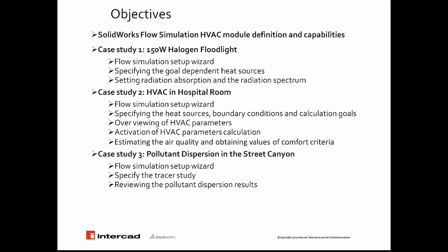The second study is specifically about an HVAC or air conditioning system in a hospital room. The main objectives are viewing the HVAC parameters and making a clear definition of them, how we can activate the HVAC parameters calculation inside a project, and also, at the end, how we can review the performance of the HVAC system or air conditioning system by looking at the air quality and obtaining the values of comfort criteria.